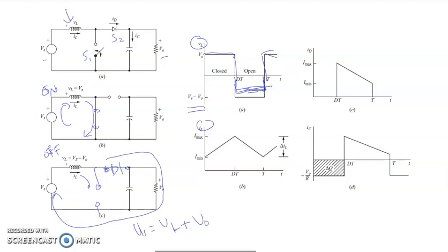This is the curve or the graph of the voltage from the inductor point of view. In terms of current, this is on, this is off. When we switch on, the current will build up. We consider the curve taken at steady state, so it ramps up from a certain level up to the duty cycle.